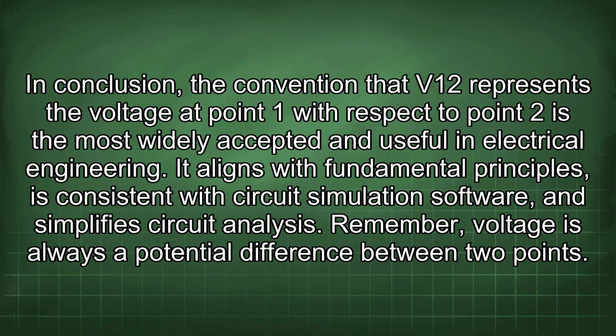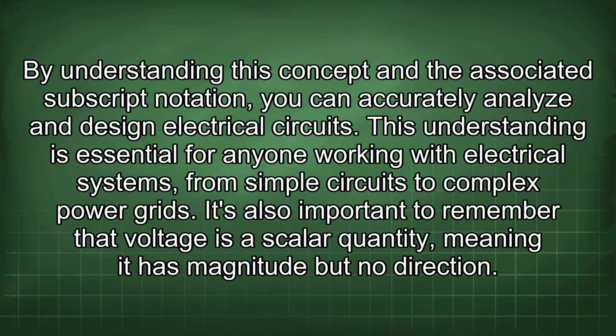In conclusion, the convention that V12 represents the voltage at point 1 with respect to point 2 is the most widely accepted and useful in electrical engineering. It aligns with fundamental principles, is consistent with circuit simulation software, and simplifies circuit analysis. Remember, voltage is always a potential difference between 2 points. By understanding this concept and the associated subscript notation, you can accurately analyze and design electrical circuits.